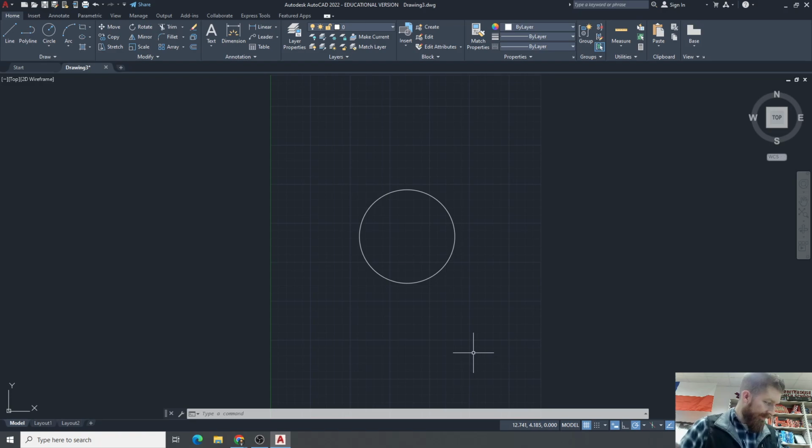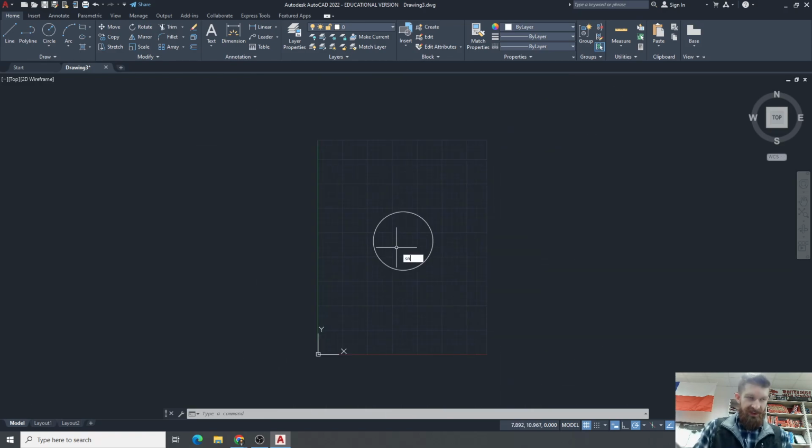Okay, the third step, set the snap. So use the snap command or snap grid of the drafting settings dialog box to set the snap type. We've done this a few times now. So when you set your snap, you can set it to whatever you want. Now the goal here, in order to achieve accuracy, you want the value of the snap to be the smallest dimensional increment that would commonly be used in the drawing. So the smallest building blocks that you would work with, that's what you want to set your snap to.